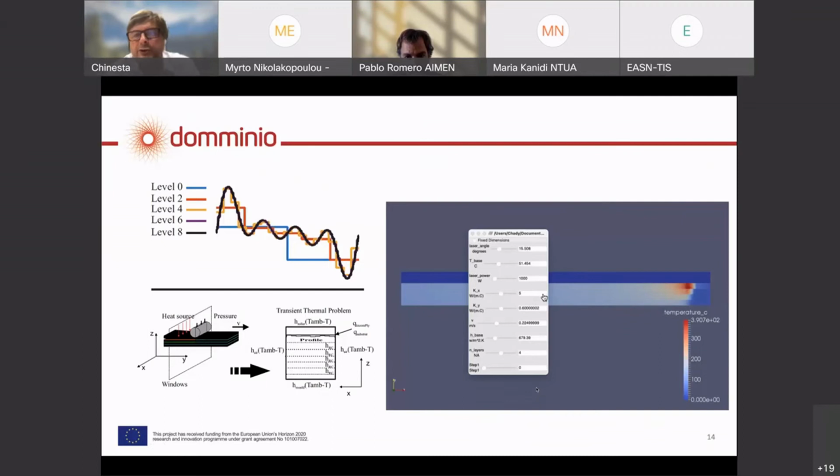Why are we introducing this thermal resistance? Because this thermal resistance increases as soon as the contact is not perfect. And when sometimes we are applying the tape on the FFF filaments, the contact is not perfect everywhere.